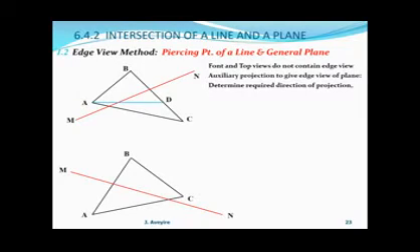we introduce now a horizontal line in any of the views. So here, in the top view, we introduce a horizontal line AD, where D is on BC. Now, for us to locate the point D on BC in the top view, we project down to locate the point D and draw the line AD.